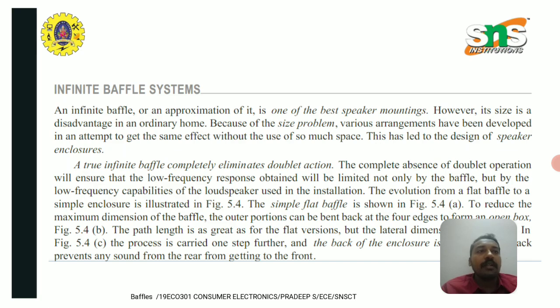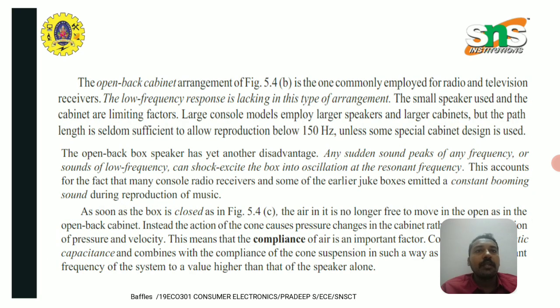The simple flat baffle is shown reduced to reduce the maximum dimension of the baffle. The outer portion can be bent back at the four edges to form an open box. The open back cabinet arrangement is one commonly employed for radio and television receivers. The low frequency response is lacking in this type of arrangement. The small speakers used and the cabinet are limiting factors. The open box speaker has yet another disadvantage. Any sudden sound peaks of any frequency or sounds of low frequency can excite the box into oscillation at its resonant frequency.